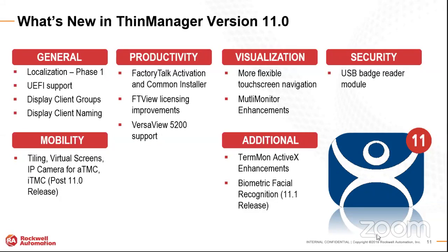And the way that happens is a lot of companies now are going that way and away from a BIOS. So we had to support that. And what actually happens in ThinManager, there's actually what we call PXE server. It stands for pre-execution environment. And when ThinManager boots up, it looks for any devices that are out there on the environment, plant floor. And in ThinManager, you have the ability of enabling that.